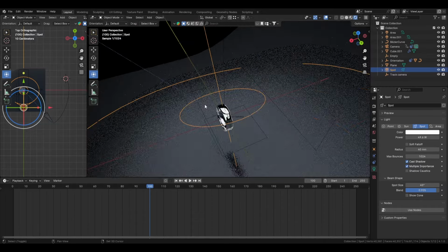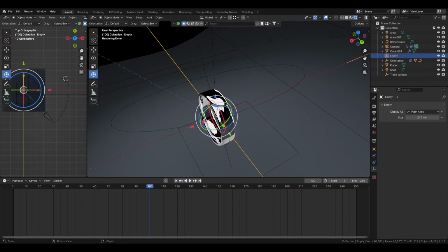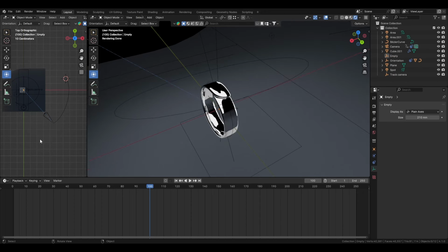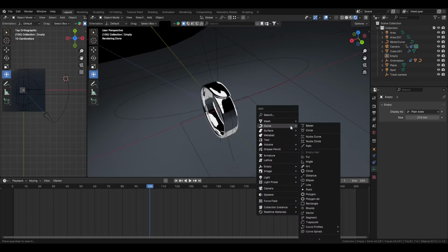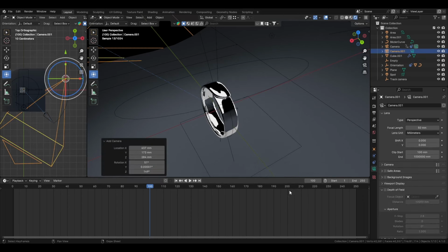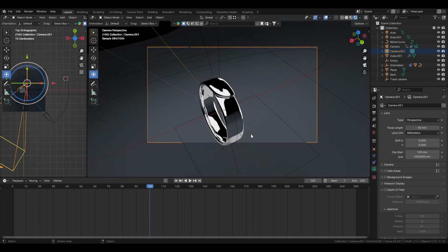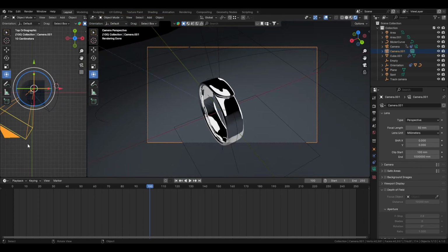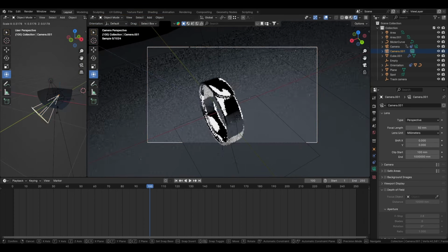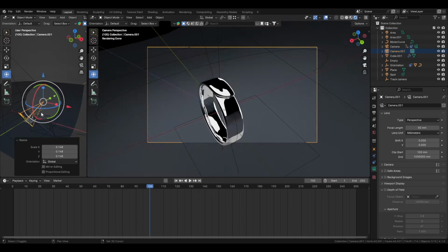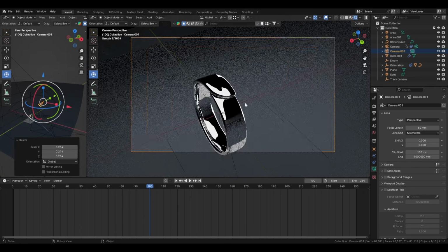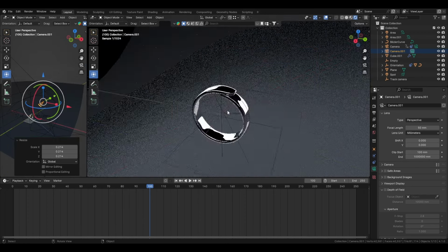Second camera, we're going to add it here. In order to add a camera where I see, we say it's Ctrl-Alt-0, but the thing is, if you do this now, you're going to move this one. We're going to first create a new camera, Shift-A, make this camera active, and then Ctrl-Alt-0 in this viewport. And then it's going to move this camera we just created to where it is. So like this here. And actually for this one, we're mostly going to move the focus of the camera.